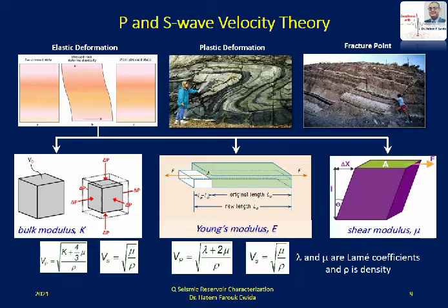And we mentioned that I have primary waves and shear waves, if you remember from the previous lectures. So the velocity of the P wave is equal to the square root of the bulk modulus plus 4/3 shear modulus over density. And the shear wave velocity can be calculated as you see, the square root of the shear modulus over the density. Or we have other expressions.